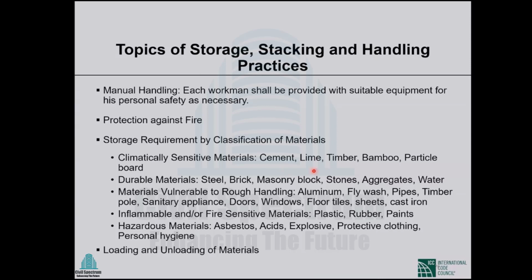For example, steel. Do you know what to do if you have to preserve steel for a long time? For example, you have already purchased steel, but your construction will start 1 month or 2 months later. What will you do? Your steel will rust. What to do in that case? I think many of you know about this, that you can cover the steel with grout, a cement water mixture. That will protect your steel from corrosion. So these details are there.